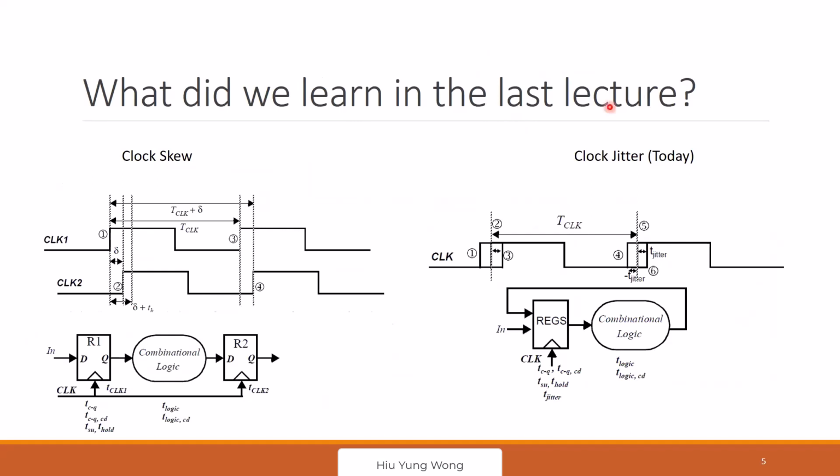So for example, the same clock signal, no buffer. It reaches here, we call it clock 1. It may have a positive edge here, but it takes some time, which we call delta, which is a skew, to reach the other register. So actually it goes up a little bit later. Because of this, it's going to affect the equation we have, how this logic can operate.